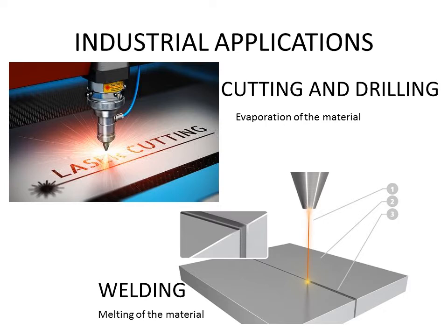In the case of cutting and drilling, the procedure or the idea is essentially the same. For example, you can see a laser head which is focused onto a metallic plate. You can see there is a lot of spark generated, and this is used for drilling a hole inside this metal. And this spark that you can see is actually not the laser light. Normally infrared lasers will be used for this purpose, and that you cannot see, but the light that you can see here is actually the spark which is generated due to the interaction of this laser with this metal.